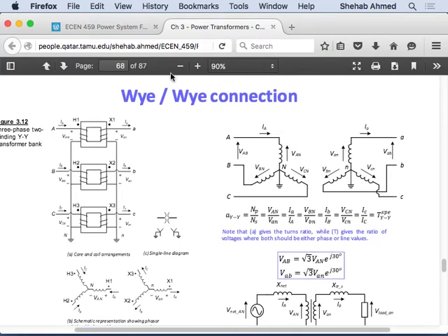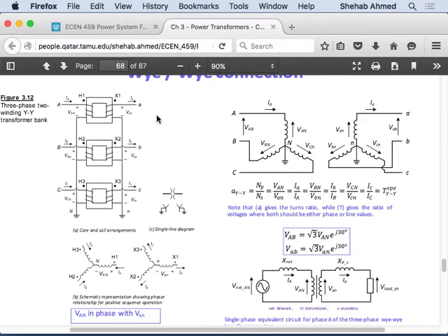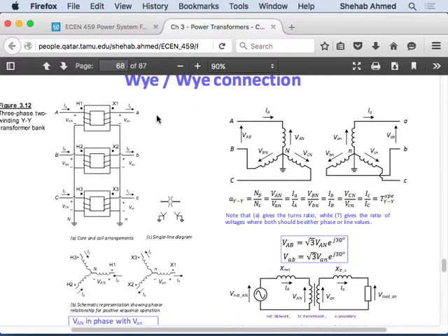Okay. So as we said, with Y-to-Y transformers, we have no problem. When you create a Y-to-Y transformer using 3 single-phase transformers, we drew it up quickly before, but here it is drawn up again. And they drew everything, both the turns that are on the same core. So this is H1, this is phase A. Primary is labeled H1, the secondary terminal labeled X1. So they drew them in parallel because they are on the same core, right? So it just complies with what we're talking about.